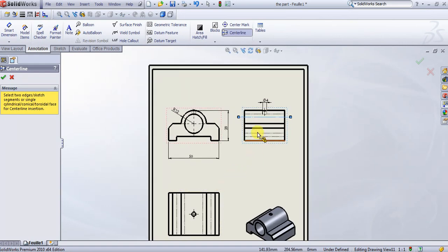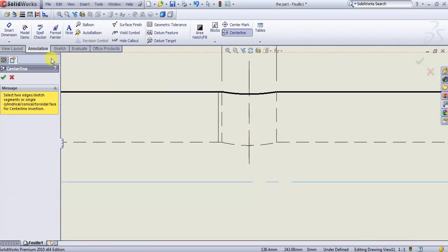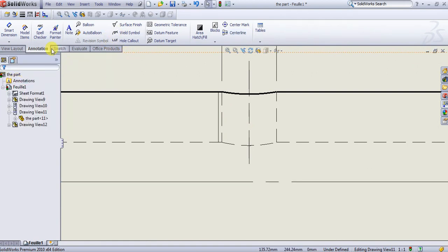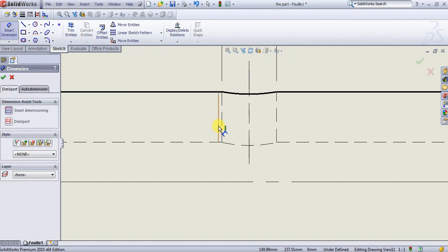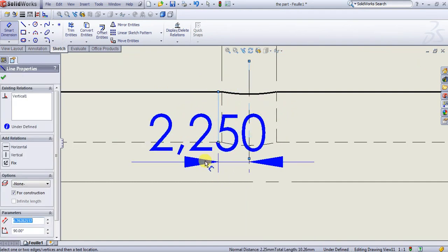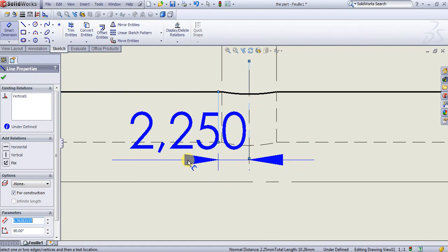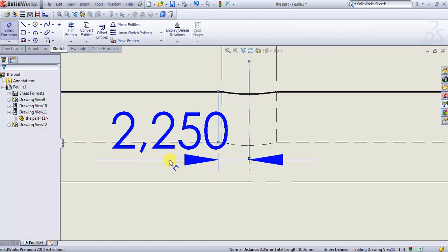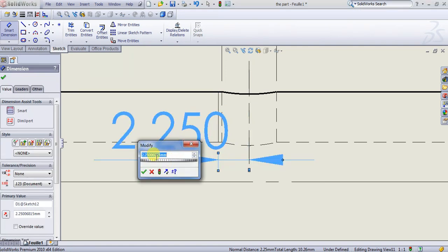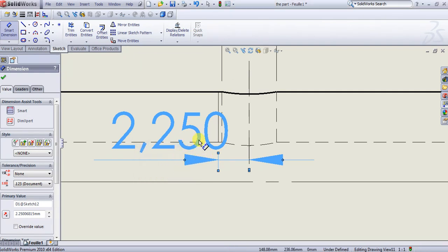Okay, so here I must continue to draw the fillet according to the standards of drawing. The fillet must be a little bigger than the hole itself. Normally it is 1.5 because it's a 3mm hole. So it's going to be 2.25. Okay.